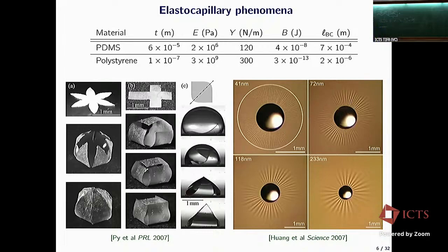So then, what is the compression? Usually you buckle, you wrinkle because you want to compress the sheet. So what is the compression? This will be epsilon. I will write it as positive, but there is actually a negative effective strain, meaning that the plate gets shorter if you look from far apart.